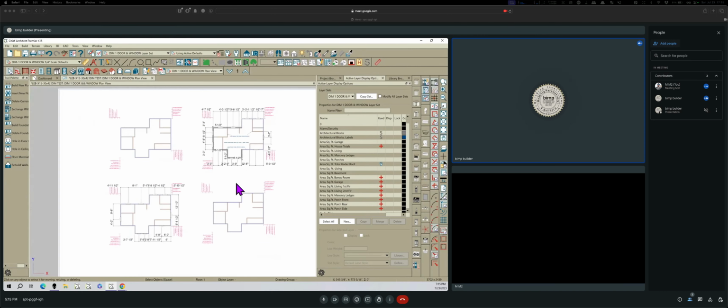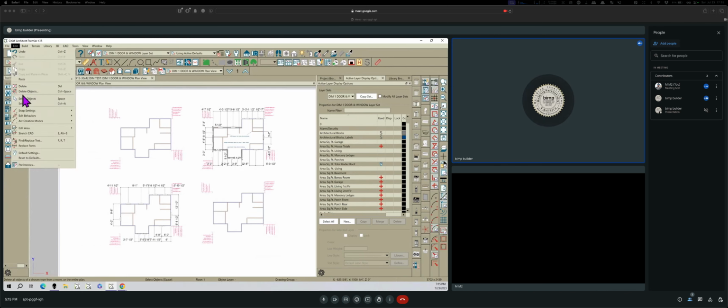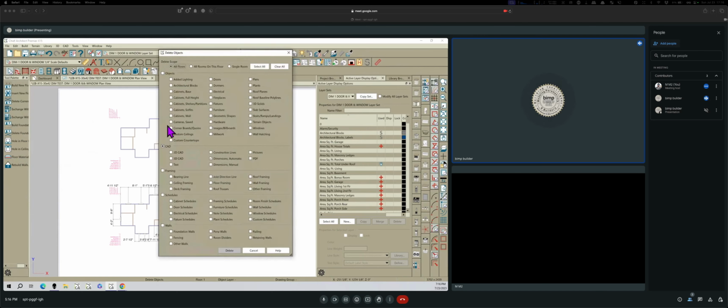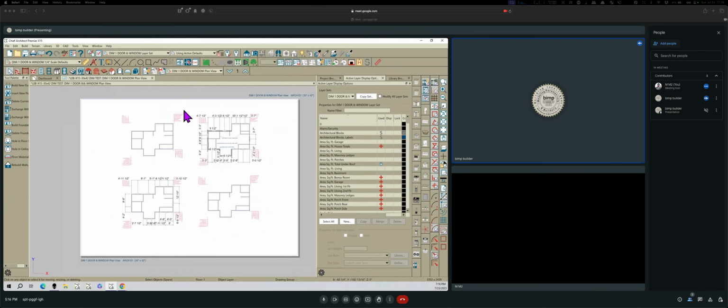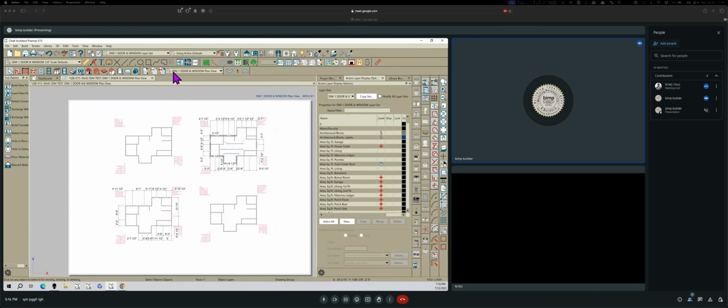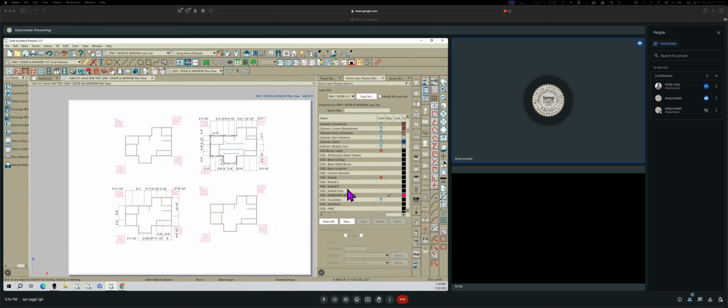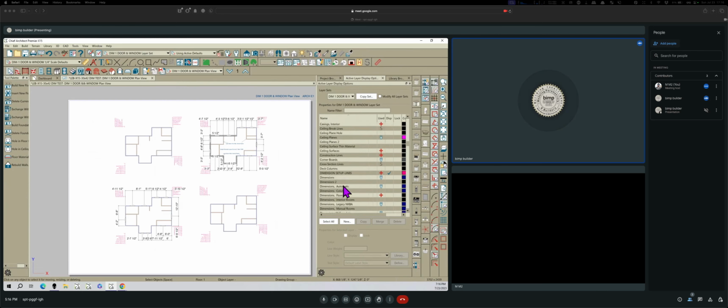Okay, so let's get this thing back to where we were talking about. Because if we're going to dimension, the goal I'm trying to do, let me just tell you, is to have these dimension layer sets right here. So when I change this, it's changing my layer set, and I have my layers all defined over here. See, I've got layers for each one of those layer sets.